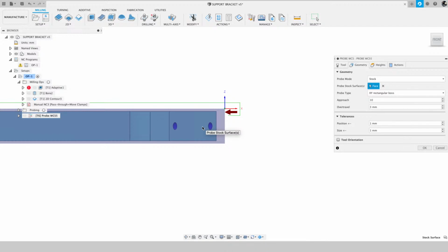It has some logic built into it. It's called safe positioning move, or protected positioning if you're using the Renishaw language. Anytime, it's like a G1 move, but the skip signal is active. So if it triggers something in any X, Y, or Z, it will stop the motion of the probe and it won't break. That's a safety built into it. Hopefully that answers the question from Ayal. Thanks, Brad, for letting me know.